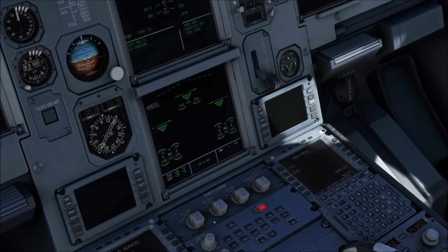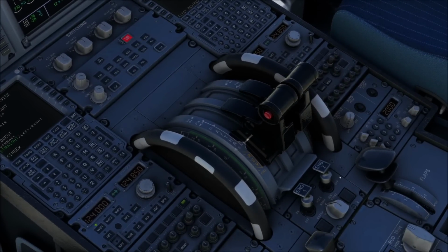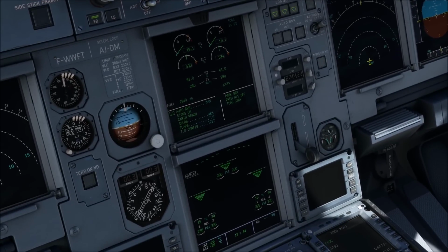You tell the ground crew that you want to start the engine: mode select, ignition start, engine master on. And once the engine master has been selected to on, you are going to tell the ground engineer, open start valve and keep open. And the start valve is built in a way that it automatically closes if you don't keep it open. So this means the ground engineer has to continuously apply pressure on his tools in order to actually keep the valve open. When N2 reaches 50%, you're going to tell the engineer close start valve and then resume standard SOP, and that is your engine started.